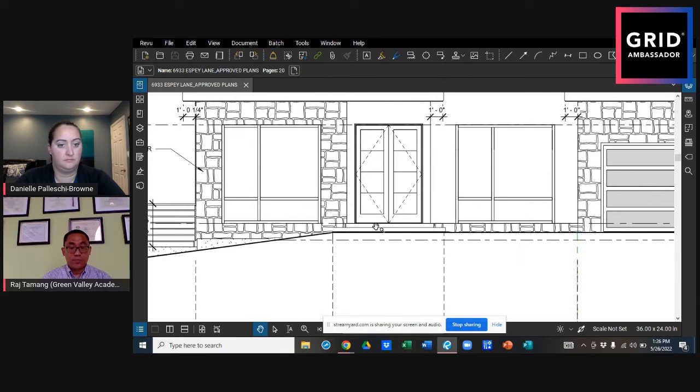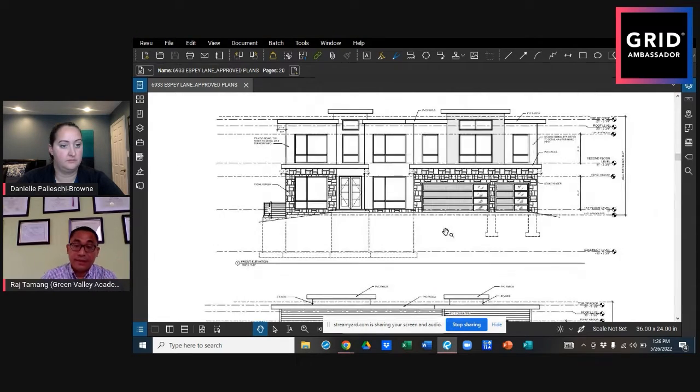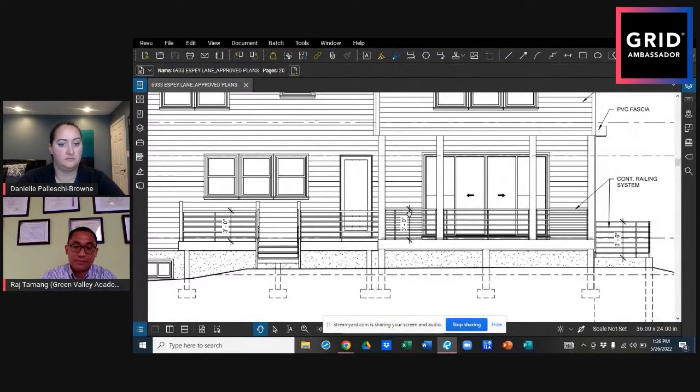this is a concrete front porch and the porch height from the outside grade is more than 30 inches, then you have to have a railing for safety. So in this case, you don't. The magic number is 30 inches. If it is less than 30 inches, you don't have to put a railing. That also applies to the deck and patio on the back. Got it. So anything taller than 2.5 feet, you have to have a railing. Yeah, from the ground, exactly. If the deck is only 2.5 feet, or 30 inches.